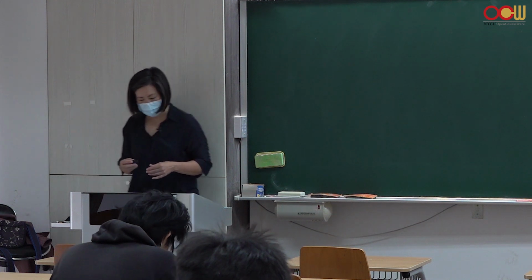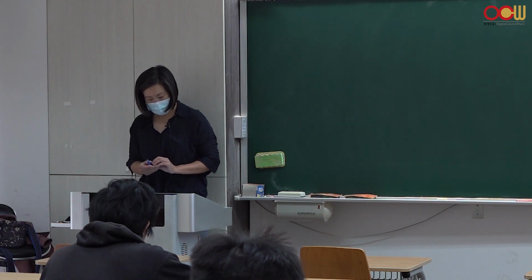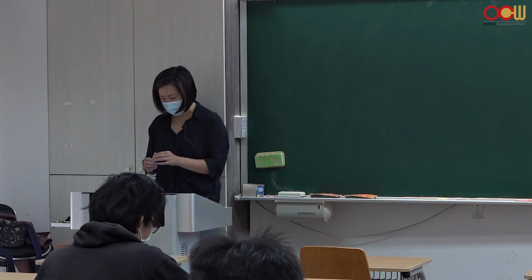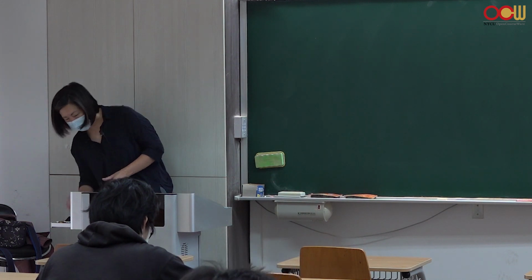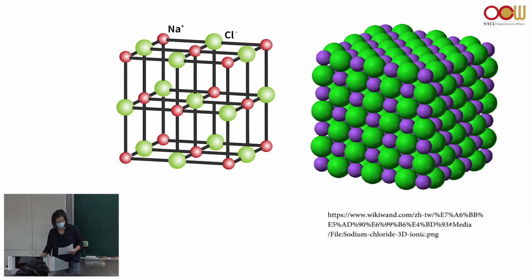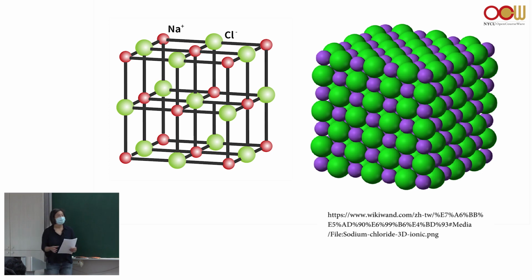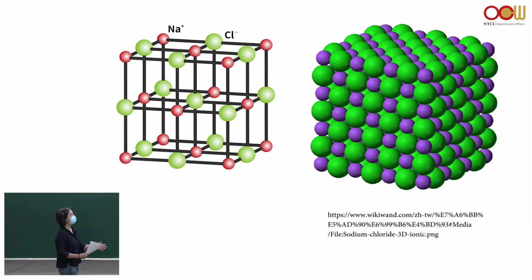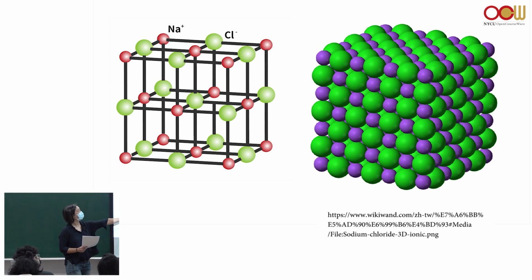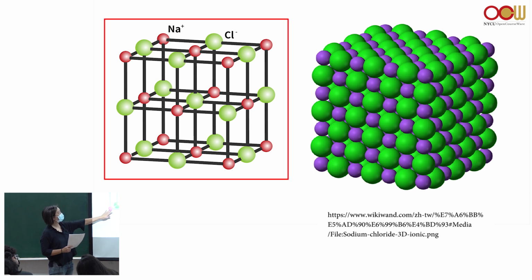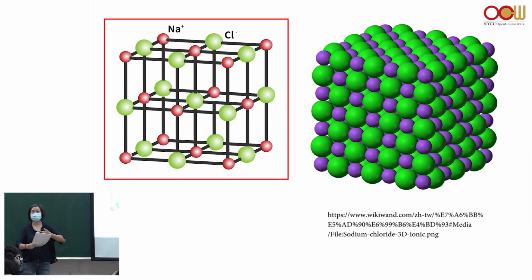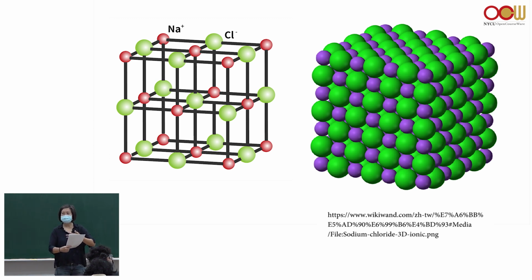We were talking about ceramics on Thursday, and I was showing you some of the crystal structures of ceramics. This is the rock salt, NaCl. This is one individual unit cell with the cation in the FCC structure, and then you can see where the anion is overlaying the cation unit cell.